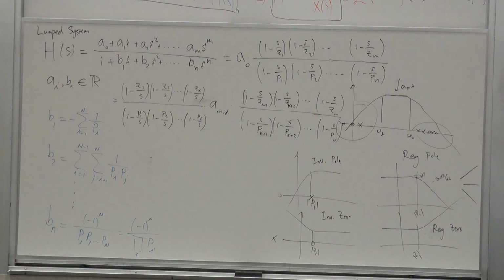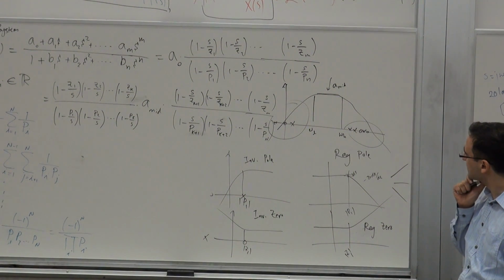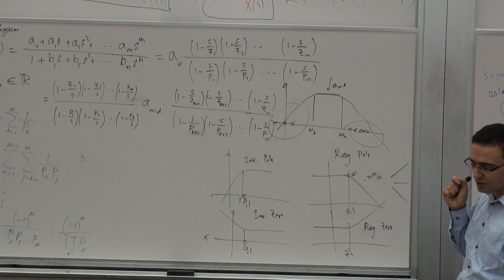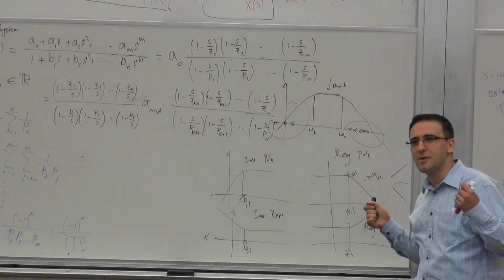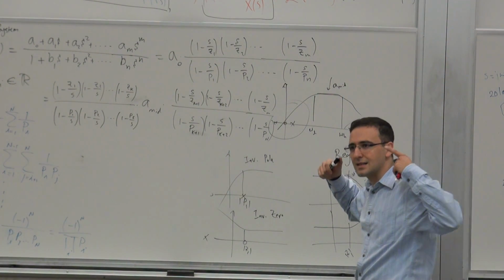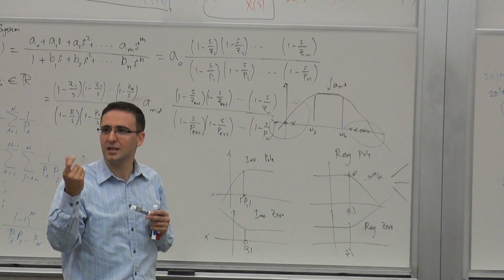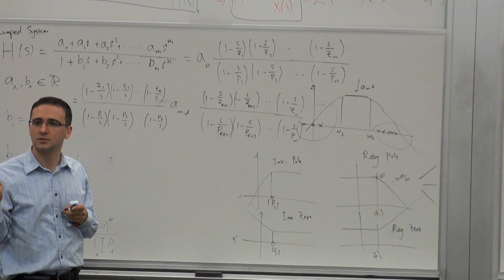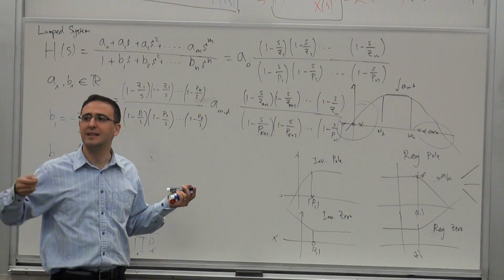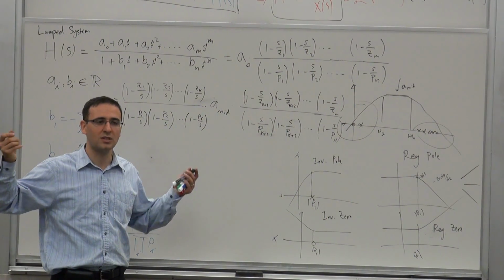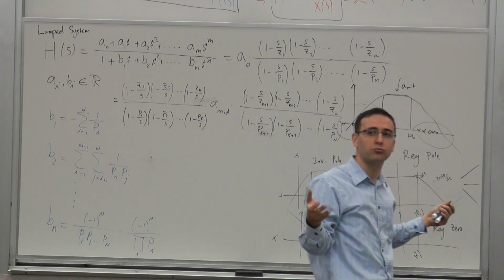Now, another comment about the general properties of poles and zeros. Let me ask you this question. Do you remember where the poles and zeros came from? Do you remember when we did the analysis, the Y matrix? The roots of the determinant of the Y matrix determine the poles. And they were independent of where the outputs are taken, because it's a property of just the network. The Y matrix is a property of just the network, not where the outputs are.